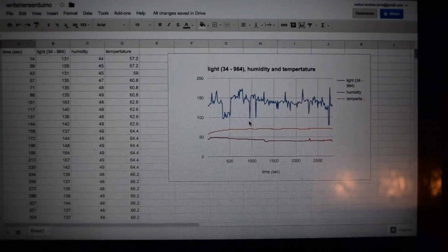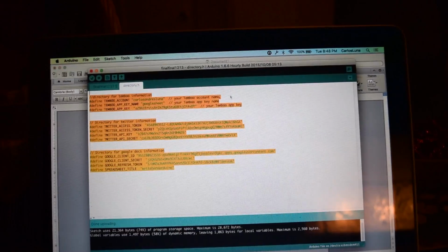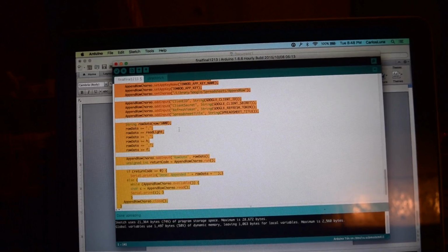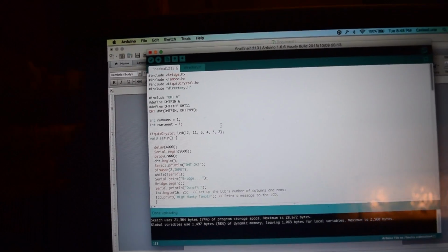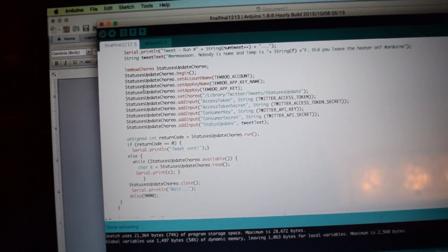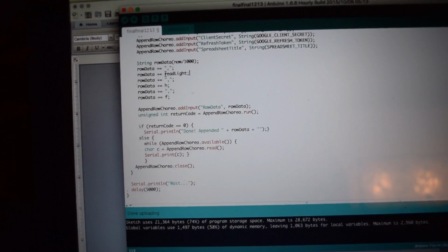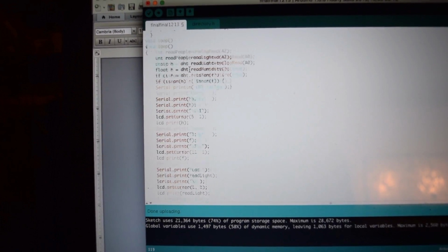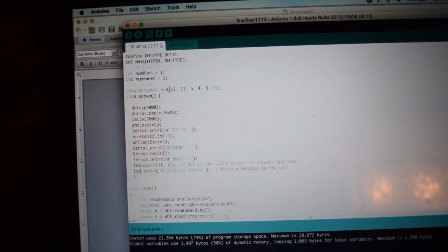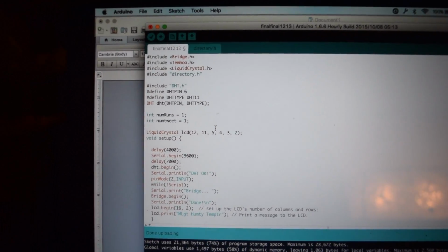We also got to work the code into the Arduino. Something interesting that happened when I was writing the code was that the device ran out of memory. So first, in the source code, I had to delete all the comments because they use some space, and I also had to use variables with the shortest names possible, and also the printouts with the shortest names possible. That's going to make some room for data.